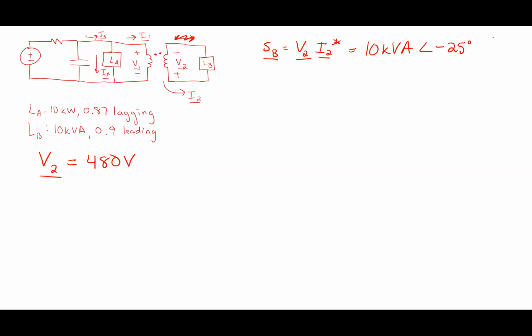Notice, to get that power triangle, I really probably could have just gone to that statement, 10 kVA, negative 25 degrees, pretty quick. I know here's the magnitude, take the inverse cosine of that, and I get to that vector pretty fast. That probably is the fastest way to do it, in my opinion. I'm just taking you through it to make sure you understand it.